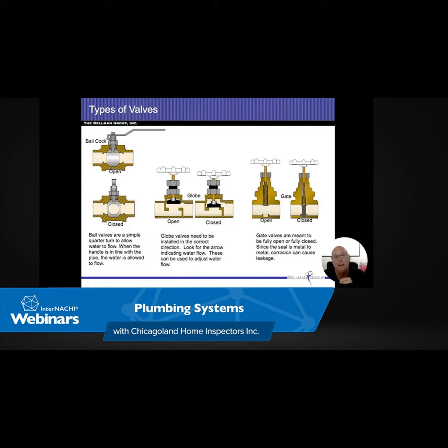So when I did this test originally, I would turn on the water to the shower or the bathtub, usually just shower, and I turn on the hot and the cold water when I'm doing that. And then I would flush the toilet and see if the water flow changed. And then I would turn on the hot and cold water to the sink and see if the water pressure changed. And nothing changed during some of the inspections that I did. And then one of them I got a phone call, which was a little eye-opening for me.